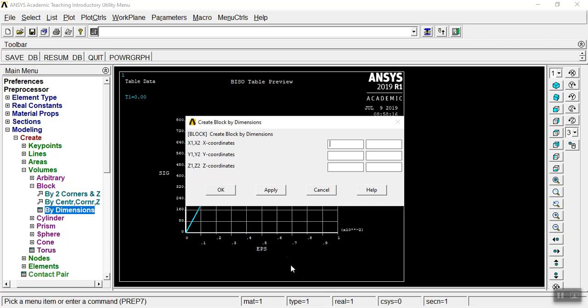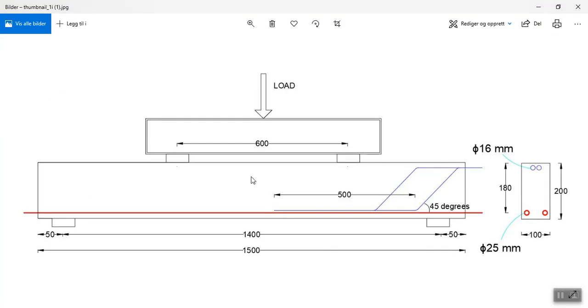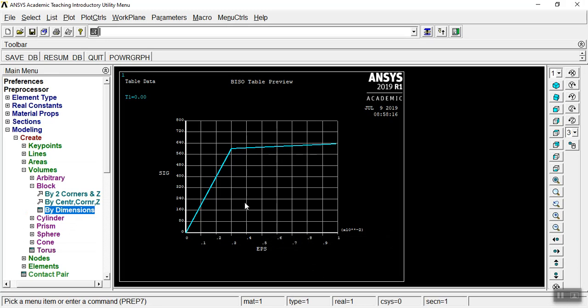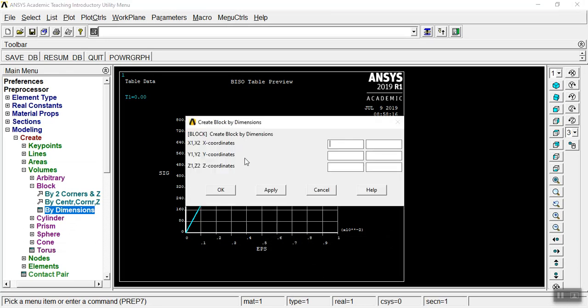Okay, so for X, I would choose the coordinate to be in the middle here, in the middle of the beam. I'll draw the beam at this base, so it will be in the middle, and then I will give the program the order to draw it. I'll show you how. So for X, it will be -50 with +50. And this is the width.